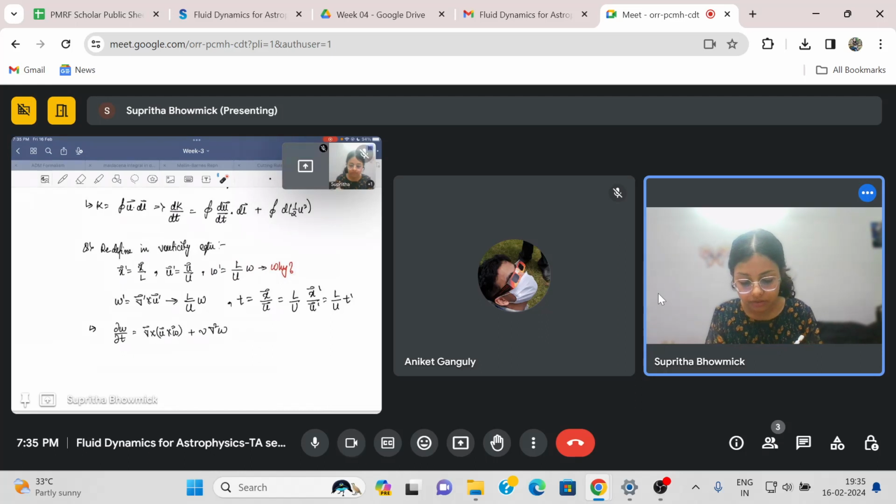The reason is omega, as you can see, is the curl of u. Now, omega prime is constructed out of the dimensionless gradient and u. So if we take this primed gradient, which is dimensionless, and curl it with u, which is once again a dimensionless velocity, we are bound to get a dimensionless vorticity.